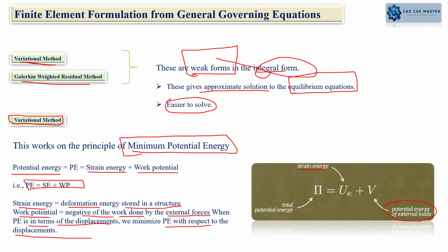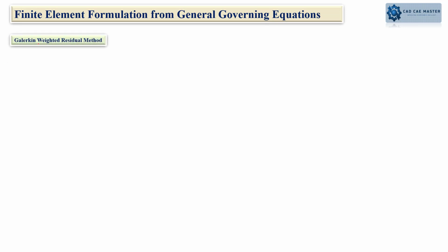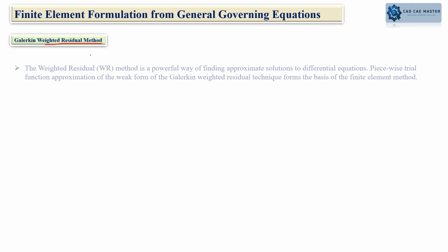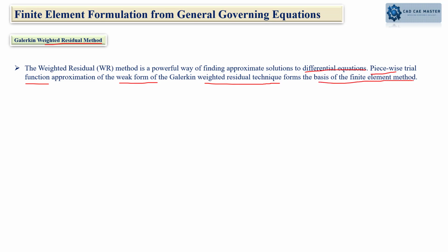Now when it comes to the Galerkin weighted residual method, what exactly does it do? This particular method is a very powerful method, and it helps us find the approximate solution for all kinds of differential equations. Here we do the piecewise trial function approximation for the weak form of the weighted residual technique, which forms the basis of the finite element method.